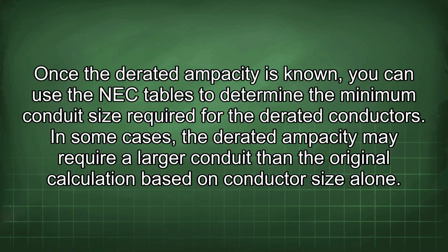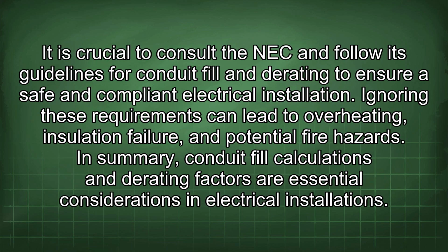It is crucial to consult the NEC and follow its guidelines for conduit fill and derating to ensure a safe and compliant electrical installation. Ignoring these requirements can lead to overheating, insulation failure, and potential fire hazards.